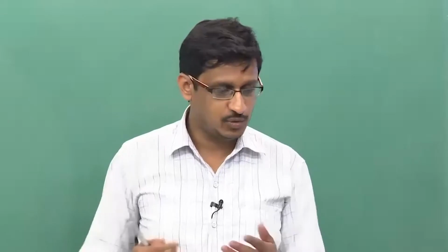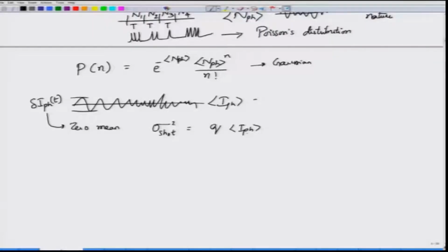Okay. However, what you are interested in is not just this one, you are interested in the total noise power contributed into the photodetector circuit having a bandwidth B_E. So, let us say this is the power spectral density. The power spectral density is essentially constant, and therefore, this is a white noise process. The value of the power spectral density is q into I_PH.